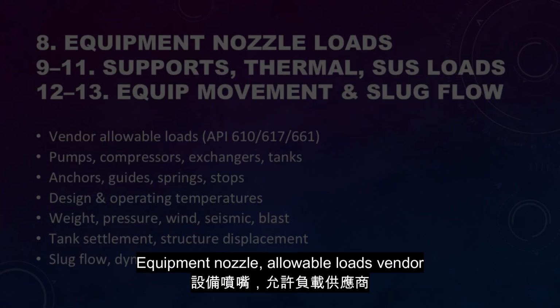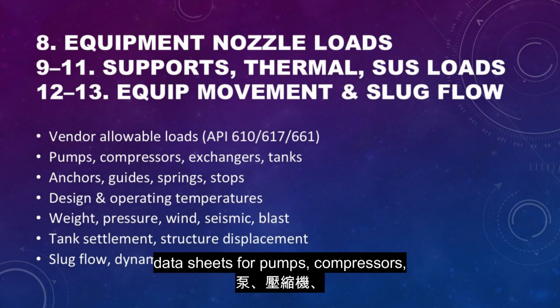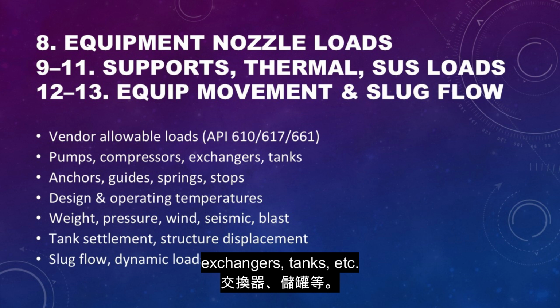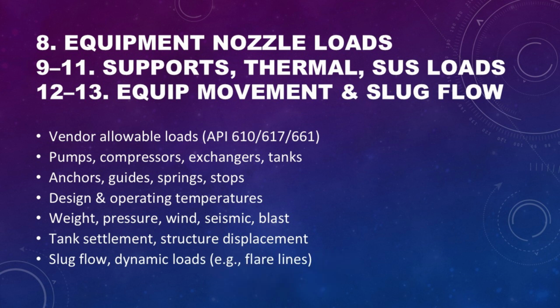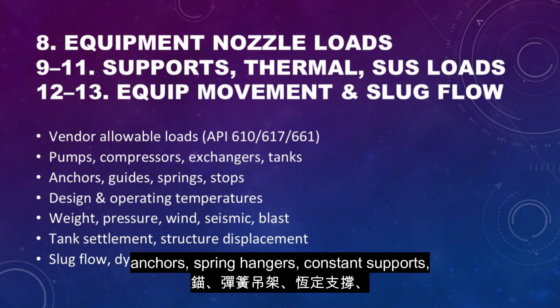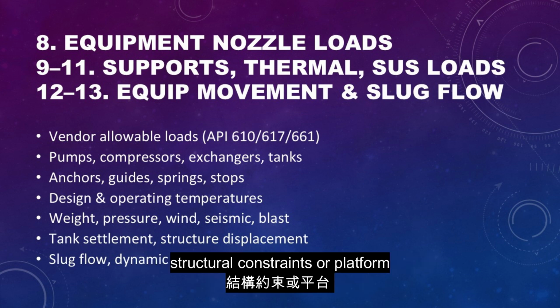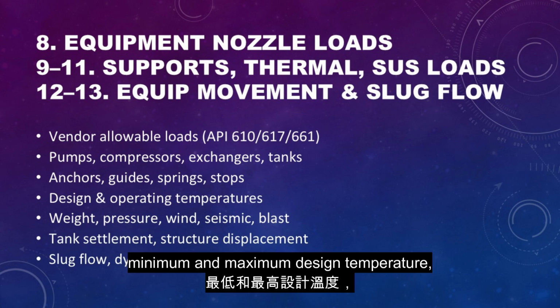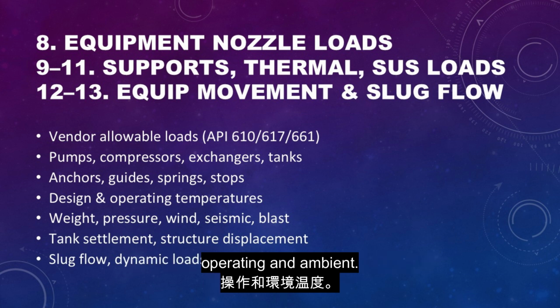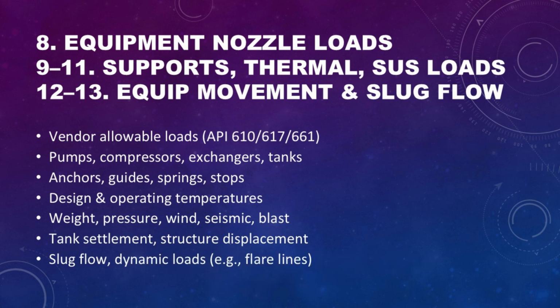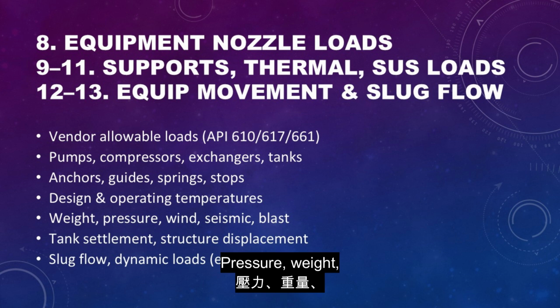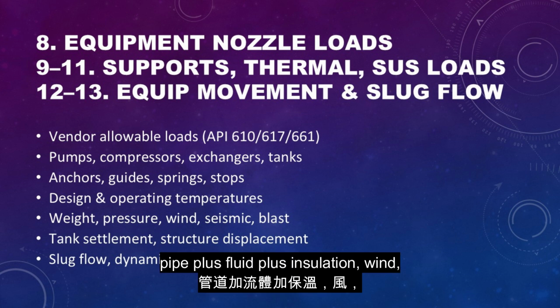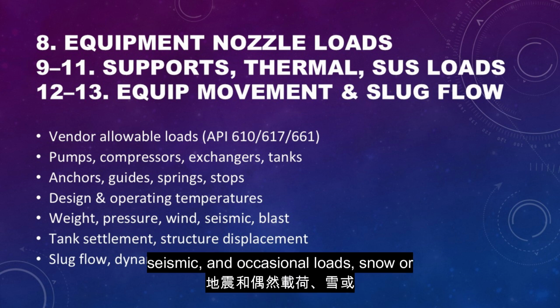8. Equipment nozzle allowable loads, vendor data sheets for pumps, compressors, exchangers, tanks, etc. 9. Support and restraint philosophy guide, limit stops, anchors, spring hangers, constant supports, structural constraints or platform integration. 10. Thermal expansion data, temperature changes, minimum and maximum design temperature, operating and ambient. 11th, sustained and occasional loads, pressure, weight, pipe plus fluid plus insulation, wind, seismic, and occasional loads, snow or blast